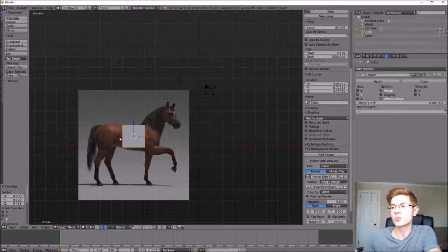And the best thing to do is break this up into sections. So first we're going to make the body, then the head, then the tail, and then the legs. So you could do that multiple ways. You could either start with one square and keep extruding sections out, or you could start out with one long shape and loop cut it multiple times so it gives you the vertices, edges, and faces to manipulate. And that's the method that I'm going to do.